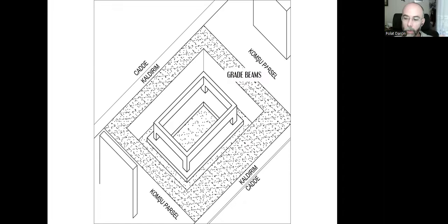This is a better foundation in terms of load transfer because we are creating a larger footing. That means that all the loads will be distributed in a better way. So if the bearing capacity of the ground is not enough, then we can prefer either one-way or two-way continuous footings. And since the footing is one big object, it will be better for us to avoid the risks of lateral forces, earthquake forces.